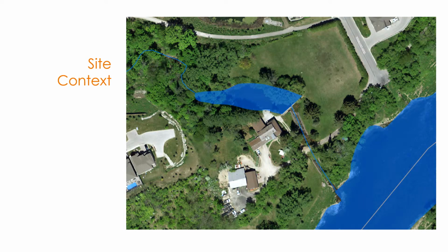To get a little closer to the site, here is where the creek intersects with the Grand River. You can observe that there is, or was historically, a large water body held back by a dam. So this led to an online pond, a dam, a pretty significant vertical drop, and the outlet was a gabion basket channel.